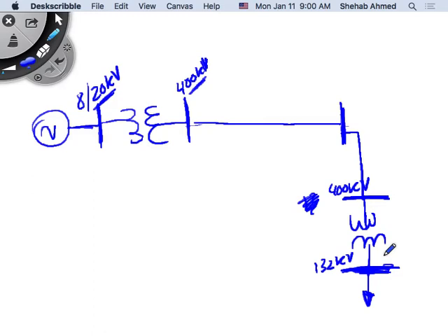And if you study power electronics, you would know that pollute means you make the current waveform not sinusoidal, right? So we saw lots of non-sinusoidal waveforms when we studied 438, right? So we would expect that a consumer like RasGas would have a lot of drives for driving the compressors, and motors are starting and stopping. So lots of variations in the shape of the current, et cetera, are happening. This is pollution to the current, right?